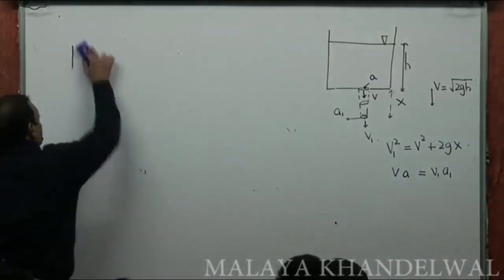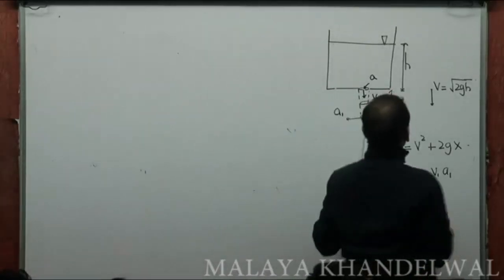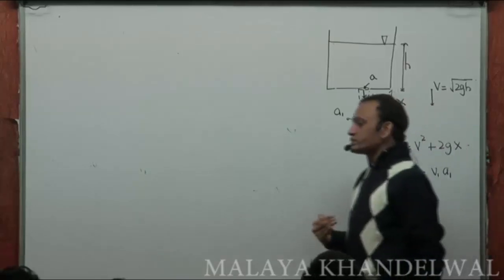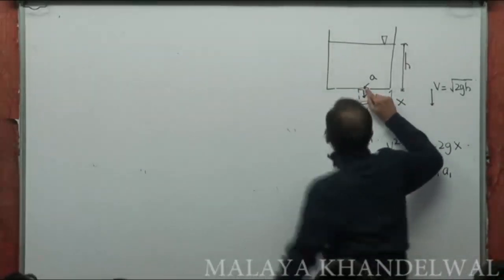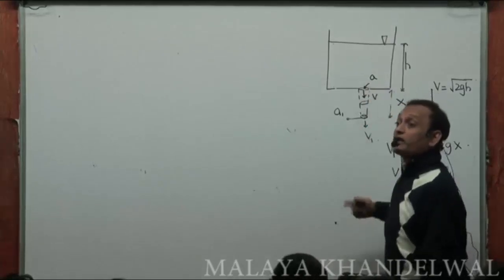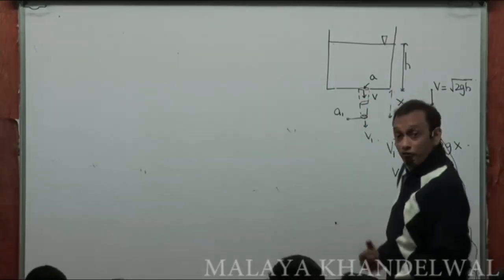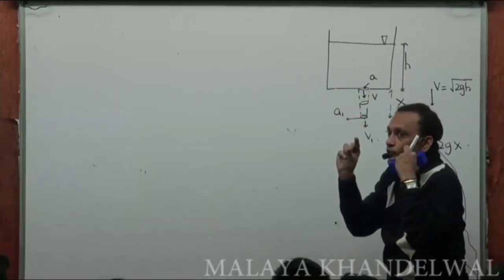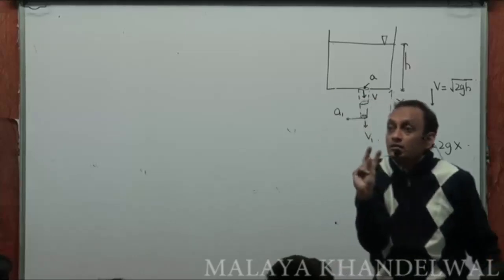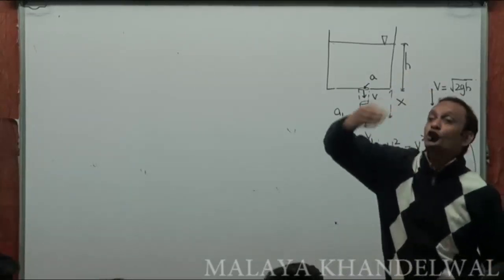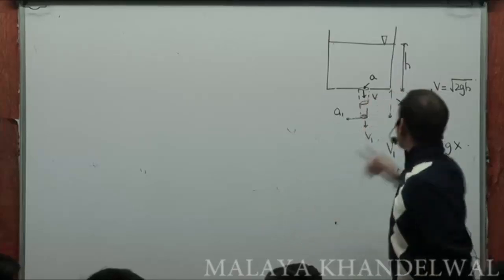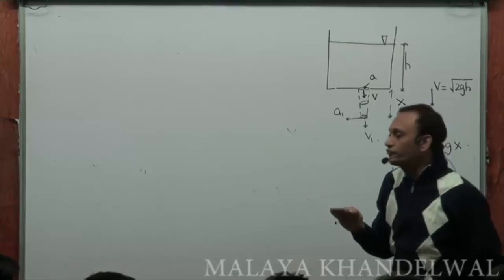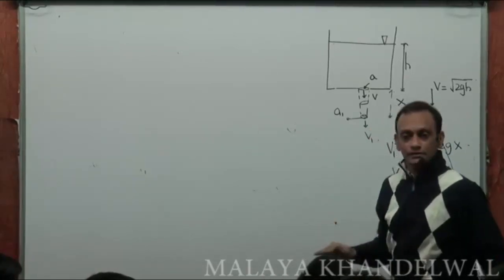There are times when during this free fall, velocities become significantly large. And when they become significantly large, the flow that was streamlined up to this point loses its streamlined character at a certain critical velocity. Therefore, you would have observed that when water falls through a tap, after a certain depth it looks a little hazy because there is turbulence that gets initiated beyond a critical velocity. So if the velocity v1 becomes significantly large, then turbulence might result and the flow may no longer be streamlined or laminar, right?